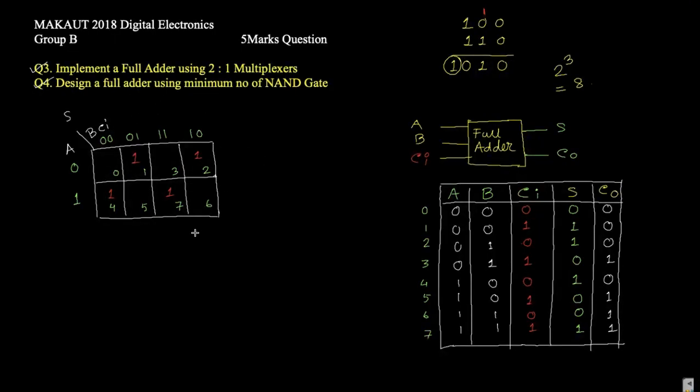So if you consider this Karnaugh map, you cannot make any group, because we cannot make a group in a diagonal like this. We can make groups of 2, 4, 8 and 16 in square or rectangular form.